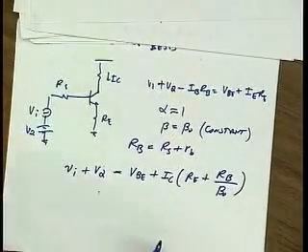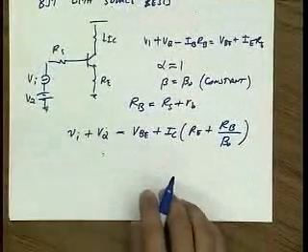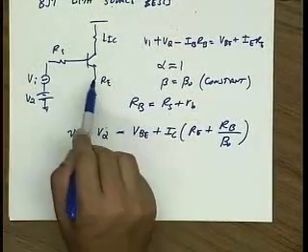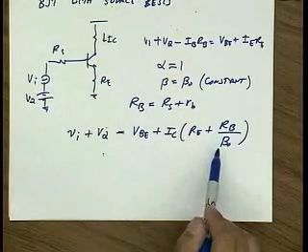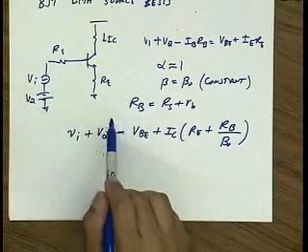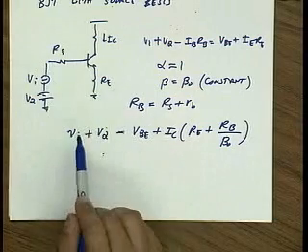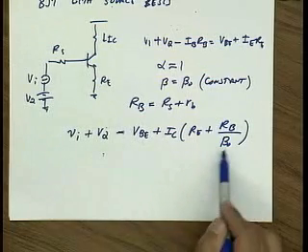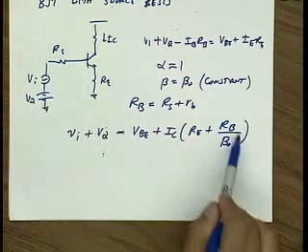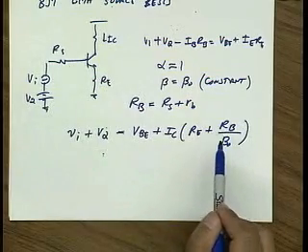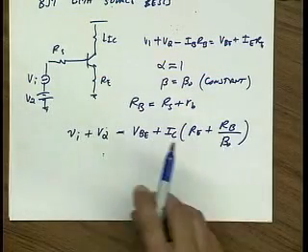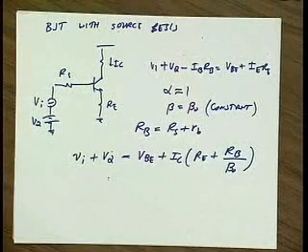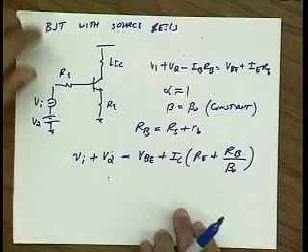In other words, as you know from your basic electronics courses, I can take a resistance and move it over to the emitter by just scaling it by beta, because the collector current and the base current are always related by beta. So therefore the emitter current is also related to the base current. So in other words, I can absorb any kind of source resistance and treat it as a feedback resistance in the emitter. Okay. Questions? All right, well, what about an emitter follower?